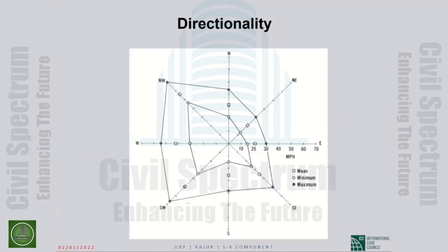Now, when we are designing a building, we are not probably going to design for the northwest wind because, as I mentioned yesterday, wind direction, like velocity, changes from one instant to the next. So wind can be along the northwest direction instantaneously, but the very next instant the wind direction will have changed and it will no longer be along that most critical direction.